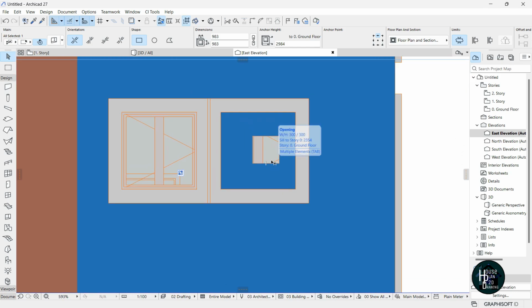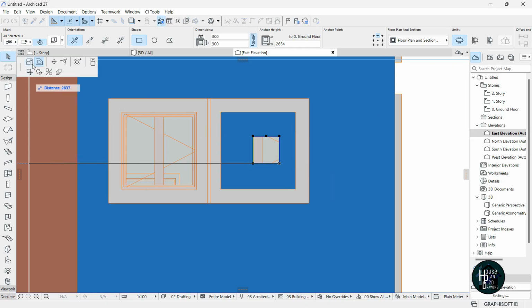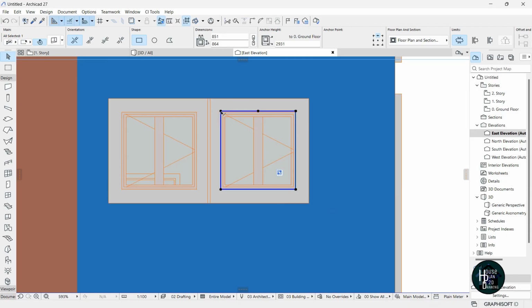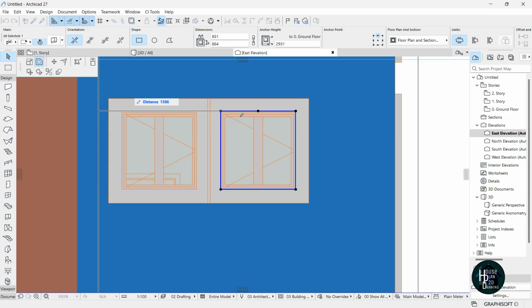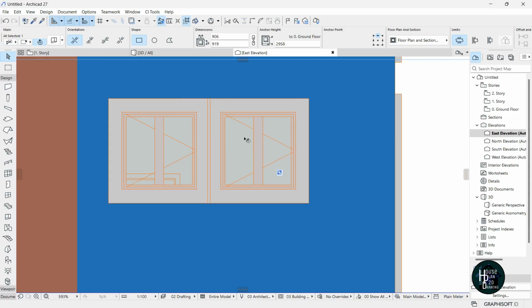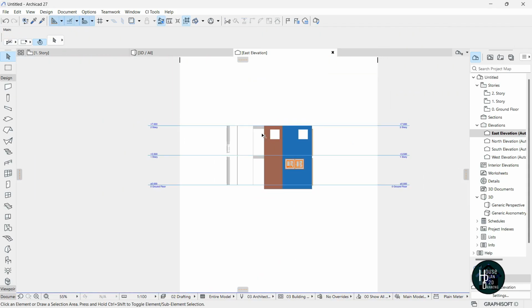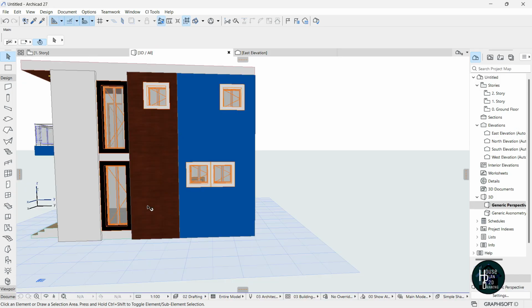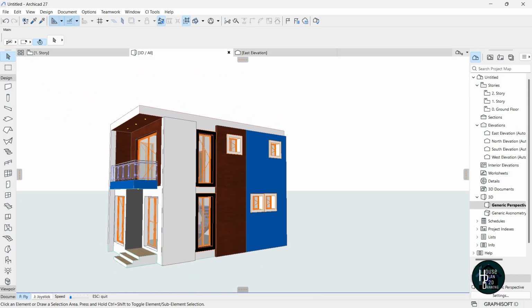But you're not supposed to be doing this if you have CI tools. Okay, click this again, click this, and then select the offset edge, click this and select the offset all edges and just click. All right, press escape on your keyboard, zoom out, go to your 3D view, and you're going to be having it as seen in this.